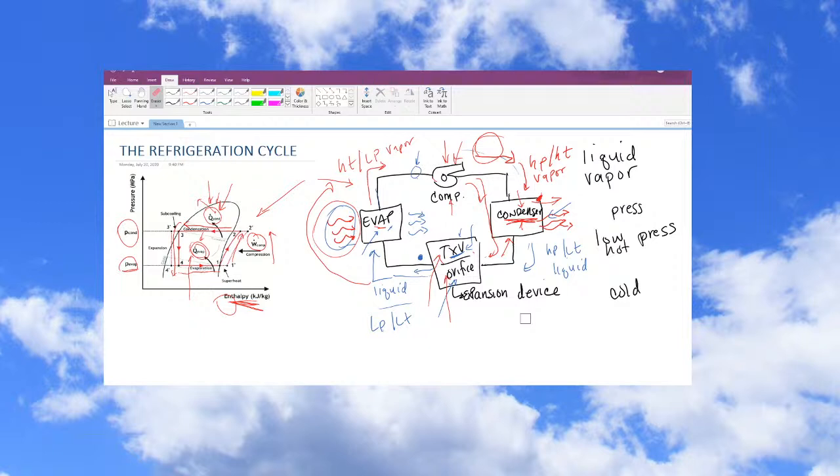I'm contemplating. Maybe I would say more like VTEC. Because with VTEC, we're adjusting the lift, the total travel of the valve, just like you would be in the variable compressor. Whereas with AVCS, you're only changing the timing. So if it was AVCS, all we'd be doing is spinning that little disc to the right or to the left, and that would give us the variable timing. But that wouldn't really do much for us.